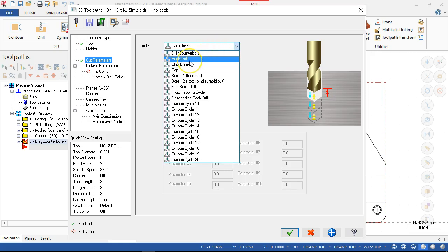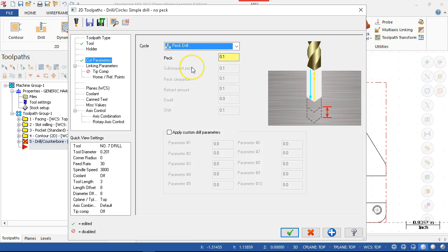On a ream, in the CNC machine, you go in, you stop the ream and then retract. Either way. I mean, it depends on material, finish, what the specification. Most of the time, it goes in. I tell it to go on a ream to feed in and feed out at the same rate. If it stops, it runs the risk of dragging the flutes up the face and leaving 6 little lines.